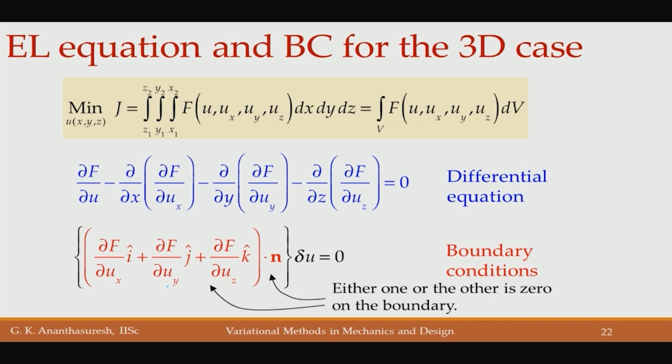Now, if we take this problem for the 3-dimensional elasticity case, let us say I have a 3-dimensional solid. It may be fixed somewhere, it may have some forces on the boundary, and there could be some forces in the interior also, like weight and centrifugal force. In that case, we can minimize this; it will depend on the first derivative. We take the linear strain u sub x, u sub y, u sub z, and u itself is a function of x, y, z, and hence u sub x, u sub y, u sub z are also functions of u. Then you get the differential equation.